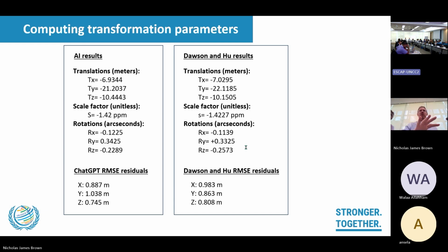So in Australia, we chose a plate motion model because it was simple. In Indonesia, you might make a different decision about how you adopt that information and how you use those velocities that come out of APREF. You might choose to use a simple model, or you might want to make a more complicated deformation or distortion model. So this is where it becomes a national decision.